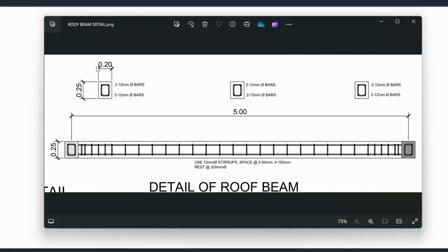And this is the reinforcing detail here at the support. You can read it in a complete plan, at support. This one is also at support. Usually this is not reflected because it is just the same as this one, just a reflection of it. So at support, these are the details of how you put the reinforcing bars in this section.